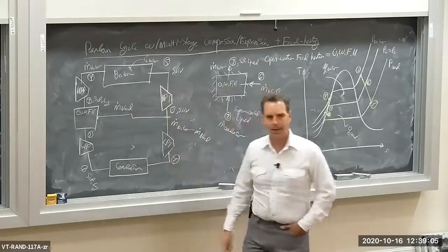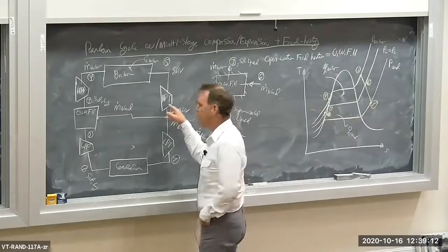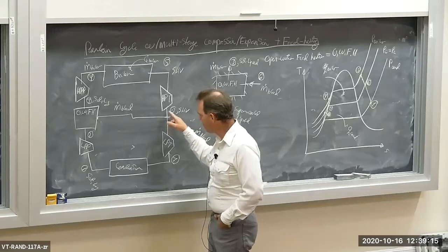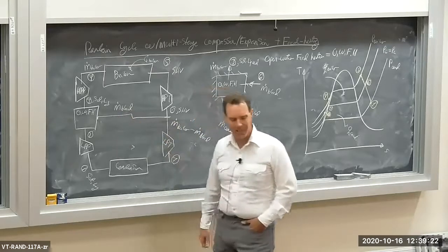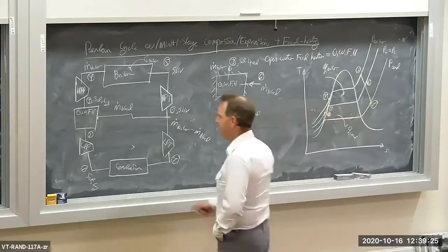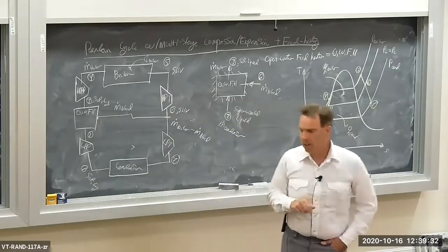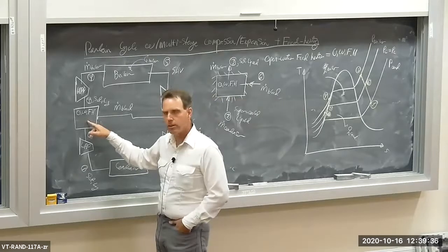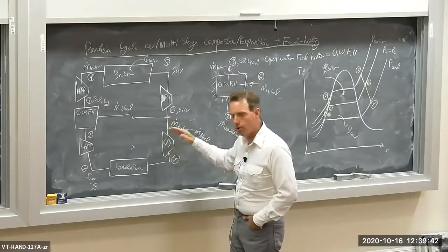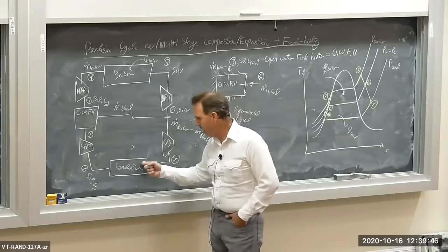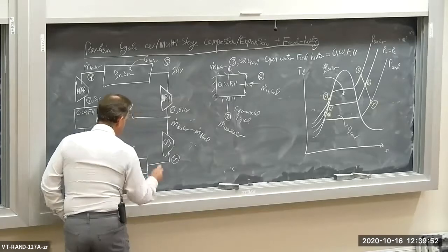We partially expand the superheated vapor. Presumably it comes out of the boiler as a superheated vapor in a high pressure turbine. Once we get through the high pressure turbine, we bleed off a small amount of mass flow, just a little bit of the mass flow, and it gets sent into this open water feed heater, okay? And it mixes with the low pressure pump outlet liquid water. And then we proceed to expand the remaining mass flow in a low pressure turbine, and then that gets sent to the condenser and we reject the heat in the condenser, Q dot condenser.